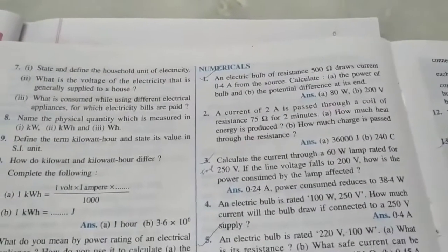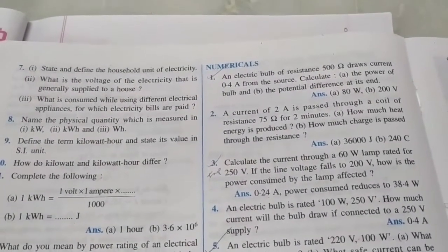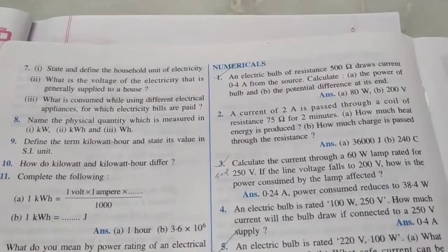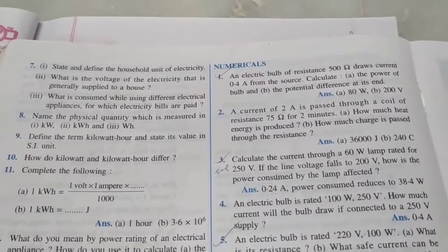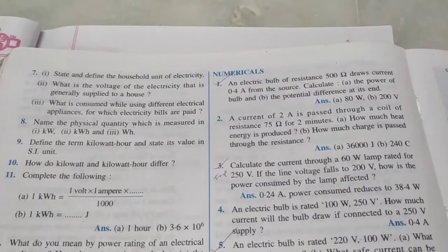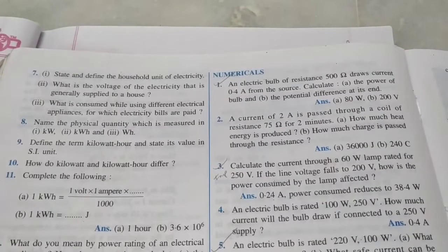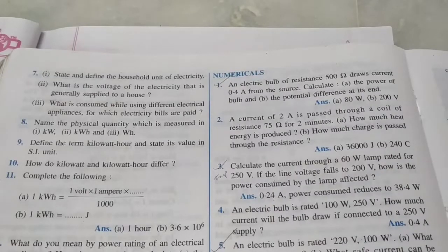Now, in the second part of the question, it's mentioned that the voltage falls. So, will the power consumed also decrease? Yes, it will. But how do we calculate that? Now, note that the current flowing through the circuit will also decrease if the voltage decreases. So, be very careful about using the formula here. Think about what will remain constant in this case. Well, that's resistance. Resistance will remain constant here, assuming that the drop in the current doesn't change the resistance much.